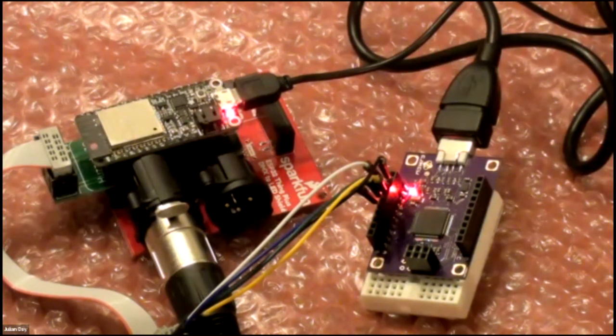Yeah, and one of our other products is an operating system for safety and security. So doing things like stepping through interrupt handlers and context switches can be really crucial to working out exactly what's going on, especially when that's coupled with trace capability. There I can run backwards and forwards through the code. I can set a breakpoint and say, run backwards, when was the last time this was hit? And then start coming forwards again.